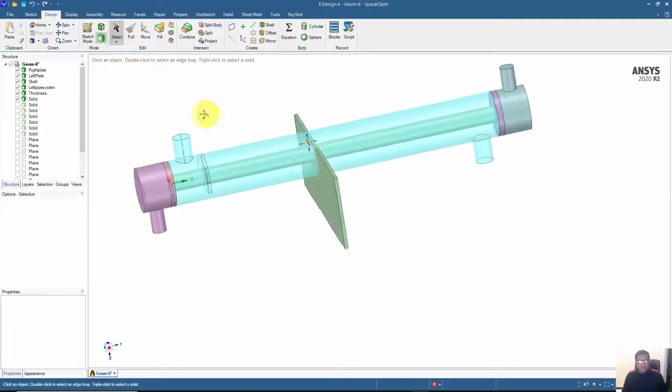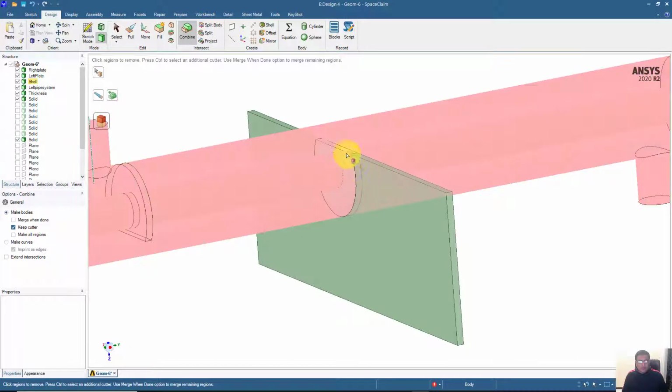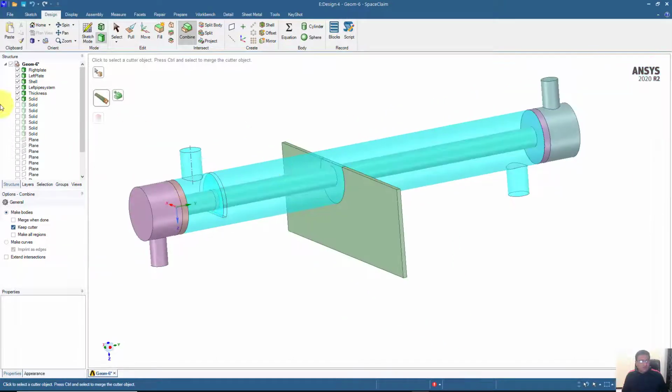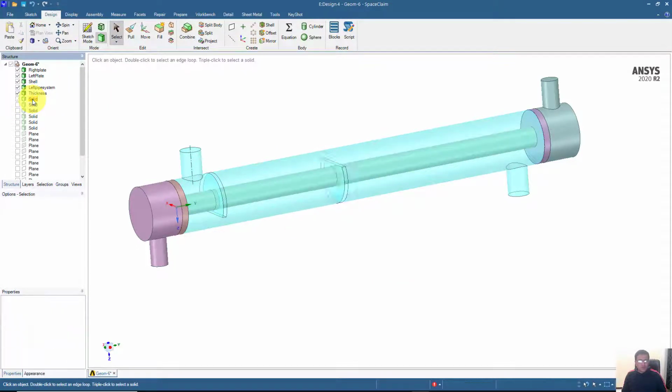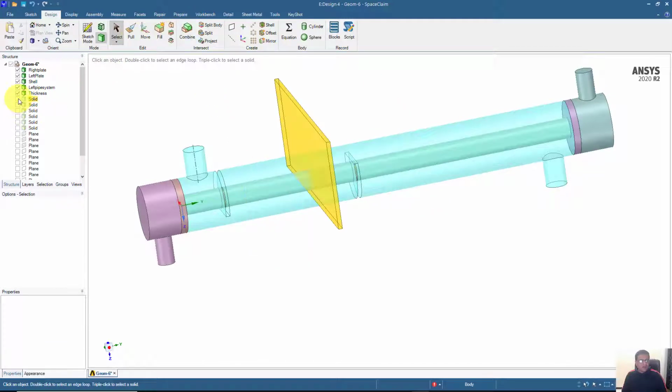And now display another plate here one by one and repeat the same process, and again I'm deleting this part here. Also choose the select option here and delete this geometry from here, and then choose the third plate. So this can be in random order, so this can be the first, then fourth, then the first, third, second, fifth, but it doesn't matter here, because the only thing which matters is that we are making the baffle at the proper locations.